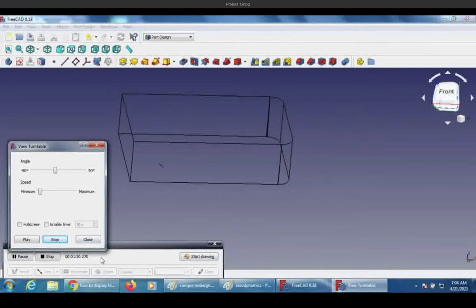That gives much better aerodynamics than this design here, because you basically have a big flat front, and when the truck is moving, the air is going to push the top box, the camper, backwards, and with this big flat surface in the front, it's just creating too much resistance, so it decreases the aerodynamics.